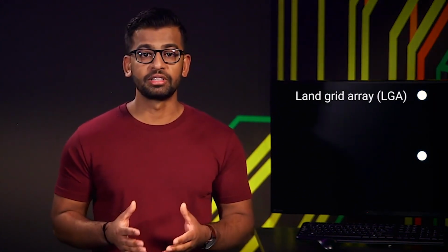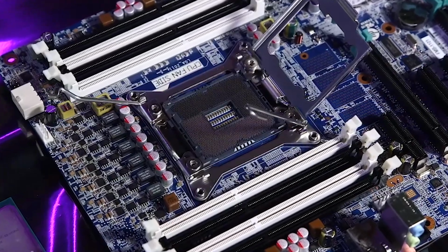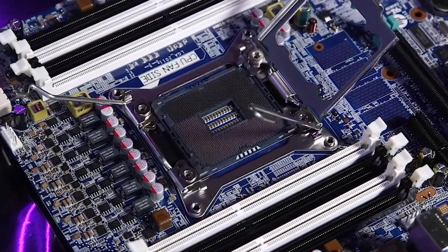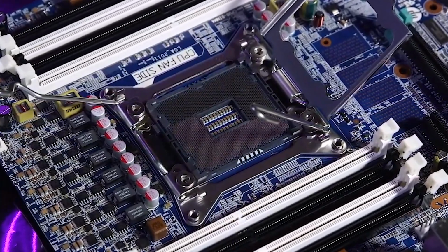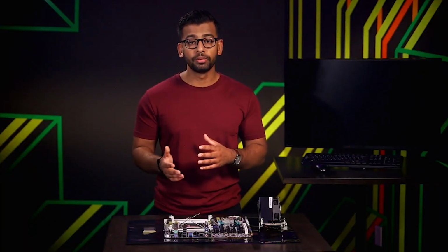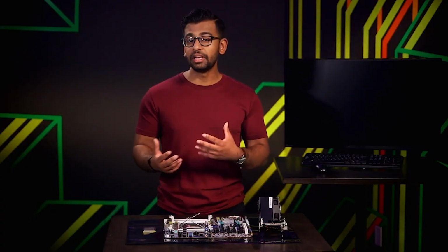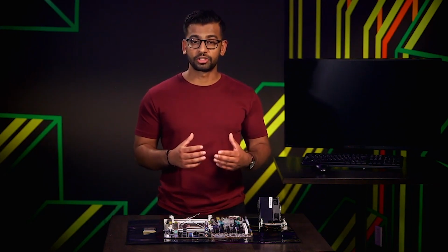There are currently two major types of CPU sockets: land grid array, also known as LGA, and pin grid array, also known as PGA. In an LGA socket like this one, there are pins that stick out of the motherboard. The socket size may vary, so always make sure your CPU and socket are compatible beforehand. When you purchase a CPU or motherboard, it'll tell you right on the box what type of socket it has. Make sure your CPU and motherboard socket also both match. If it's not listed on the box, you can go to the manufacturer's website, where it usually lists what types of CPUs are compatible with the motherboard. The other type of socket is the PGA socket, where the pins are located on the processor itself.